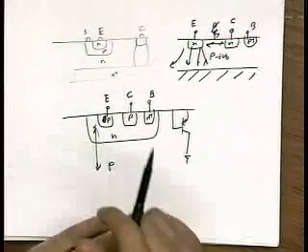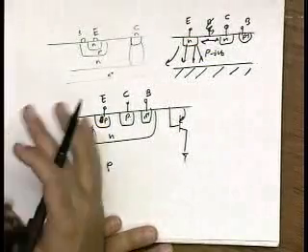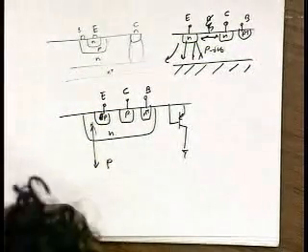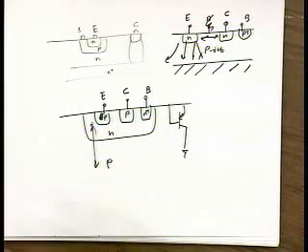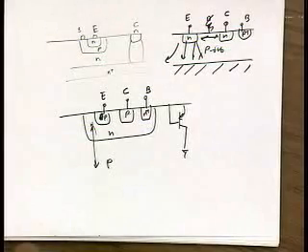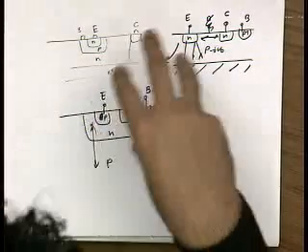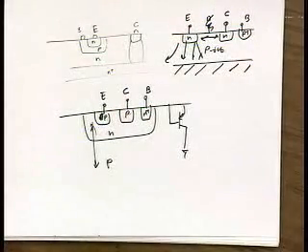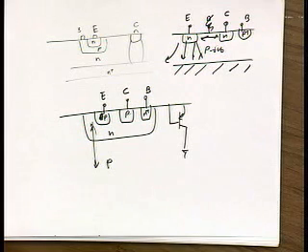Well, it's interesting. So this is the conventional way of thinking about it. But if you look at the Journal of Solid State Circuits, you'll find that people have actually built decent PNPs and NPNs in traditional CMOS processes. And if I remember, I'll give you guys a link to that article. So it's true you're not going to get a great device, but you can actually get a pretty decent device. And for many applications, you end up with sufficient FT and sufficient gain that you can actually use it.